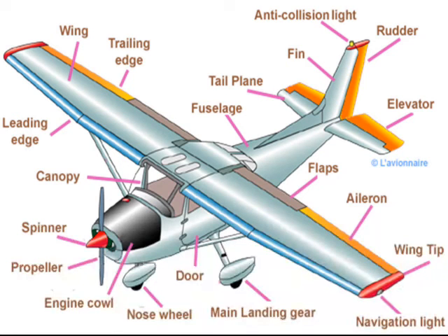The three controls. An aircraft in space can move in three principal axes, namely the x-axis, y-axis, and z-axis, as shown in the figure. The movement of aircraft about the x-axis is called lateral or rolling movement. This axis passes through the center line of the nose and tail of the aircraft. A hinged flap known as aileron is fixed. So these are called ailerons.